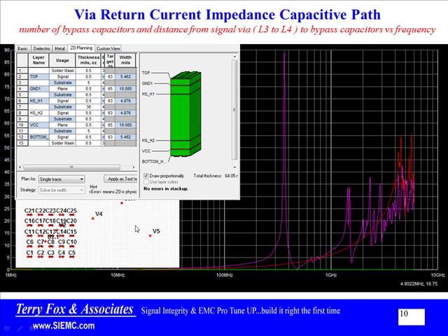So if you take a look at this, what I've got are two different stitching vias. One is a stitching via that's sitting out here. Not stitching via, but vias. I've got one sitting out here, which is this via 5, and it's a long ways from the capacitors that tie ground to VCC, because I can't use a stitching via when I'm changing the voltage of the reference planes. I have to put capacitors between these things. We call them bypass capacitors. So here's the 6-layer board, so I go signal, ground, signal, and then signal, power, signal, typical 6-layer stack up. That's what the stack up was.